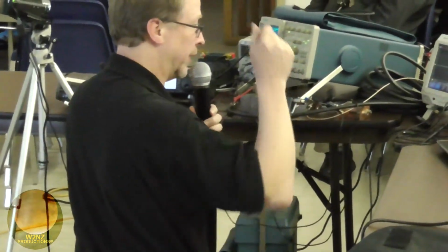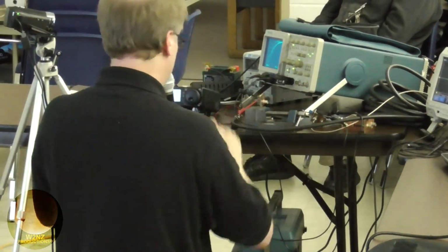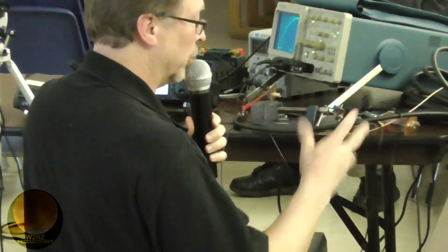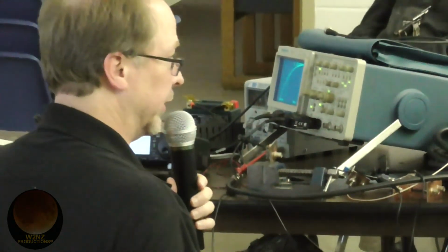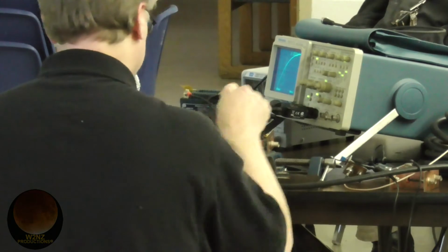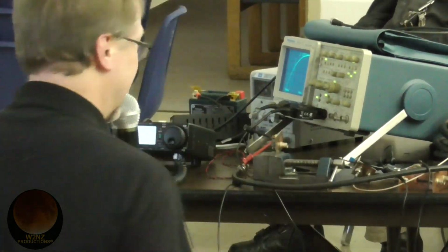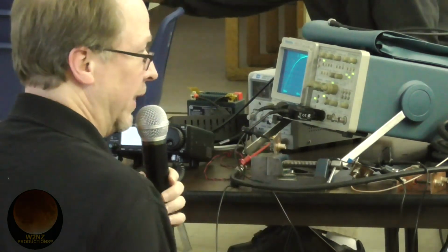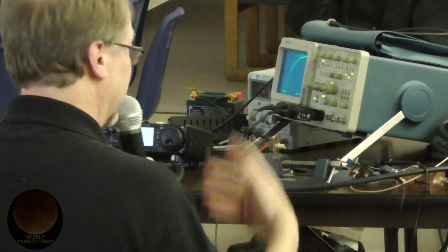Now I had a 1K resistor, so 1,000 ohms, and a 1 microsecond time. Do the math. That's a 1 nanofarad capacitor. And if you look at it, it says 1 nanofarad on it. If you don't take my word for it, you can come up and look at it later. But here's a simple way of measuring capacitors by looking at the RC time constant.